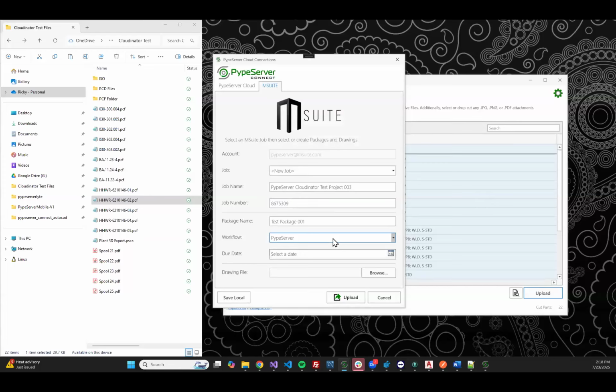Everything under 6 inches will go to a station called Cut Table. Your defining factors there will probably be different, but the majority of the machines that we support, as far as plasma cutting goes, support 2 or 2.5 inch as the minimum. And anything larger than 2.5 or 3 inches is a pain to pick up by hand and put onto a tire stop.